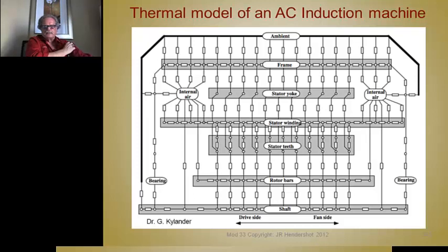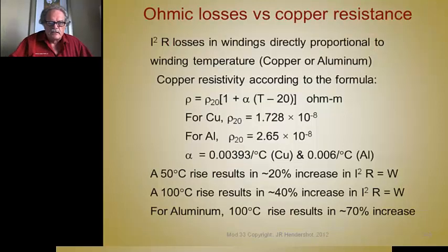One time I had a contract from the Air Force, and we took a bunch of motors that were constructed different ways, and we measured what the resistances were for the material transitions. We tried to make a database so that if you were going to use a lumped parameter model design, you would decide how you were going to make the motor, go into this table, and look up the right resistance values for the material transitions. But you still don't know if the motor's made exactly the way you thought it was going to be made. You still have to measure it.